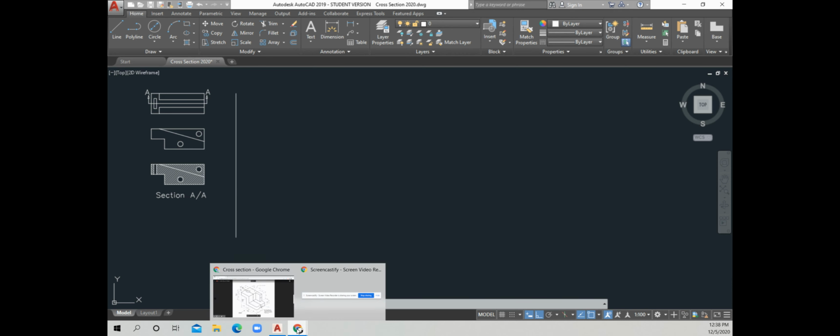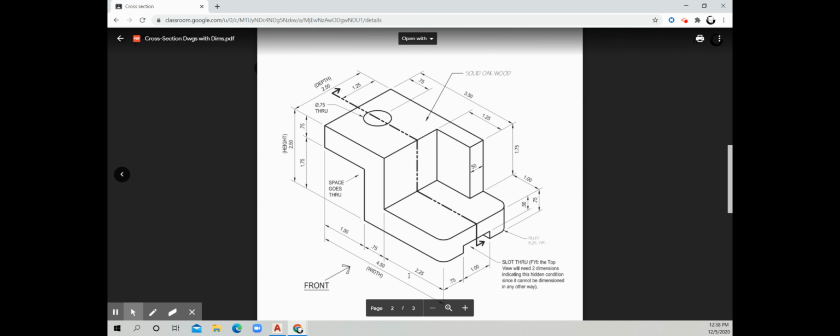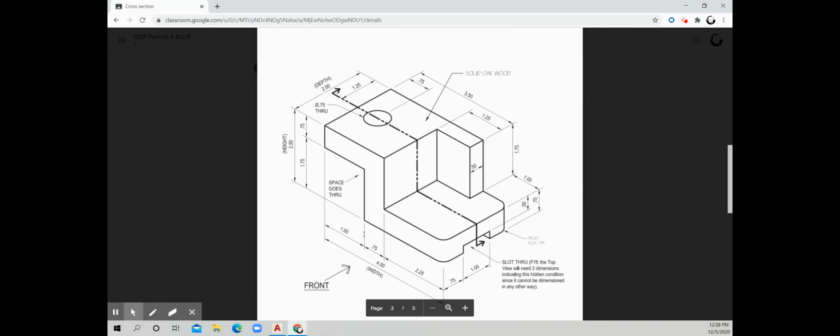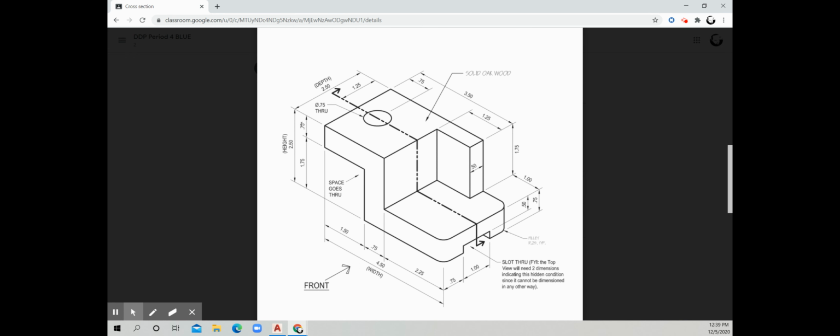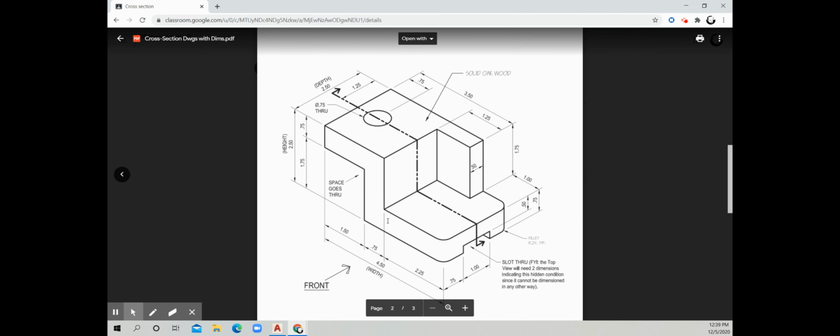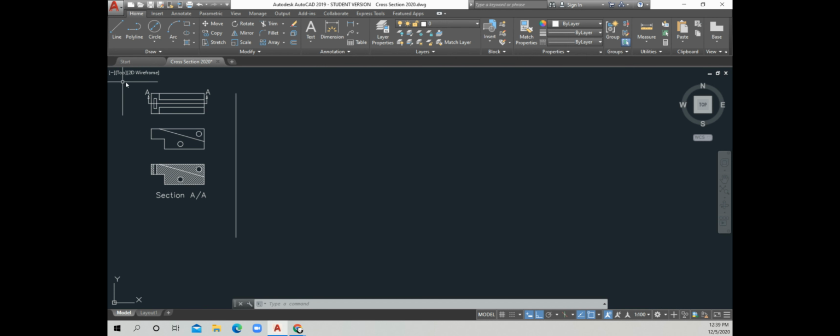So we're starting with the front drawing here. As per usual, I like to start with the bottom line right here. Now, despite the fact that there's a curve here, or radius, when you look at this from the side, it's still going to appear to be square. So looking at 4.5 for a width for the whole front side here. We are also looking at an overall height of 2.5. All right, so let's remember those two measurements, and let's put the lines in for that.